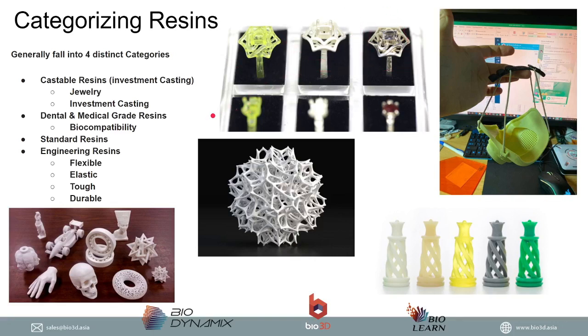So over here, for example, you've got the initial 3D printed jewelry part, the ring, and then over here it's actually been cast, and then over here it's been polished and cleaned up, and the stone's been added, for example. And so this would be the workflow. Now if you think about it, traditionally the way that this would have been created would have been exactly like your PFM technician. They would have used wax and built that up. And if you can imagine how much time saving this has, it's incredible.